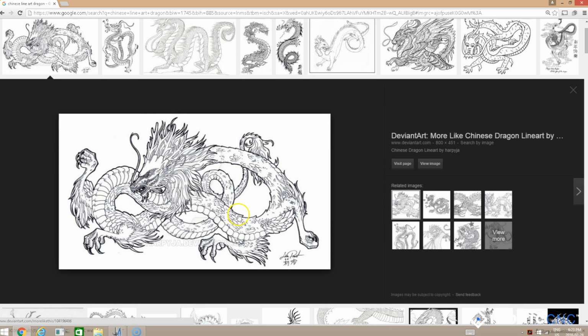If you look at how fine this detail is here, that can be somewhat problematic when we're doing this bitmap to vector conversion. The problem ultimately is that the machine is going to try and machine all that fine detail in. Not only is it going to take an extremely long time to machine, but imagine if your material wasn't completely flat. There may be portions of this that don't machine at all. While we may put a piece of material through a planer or a sander before we put it on the machine, by its nature, wood is never completely flat, and so you may have these little small dips and dives in the material.